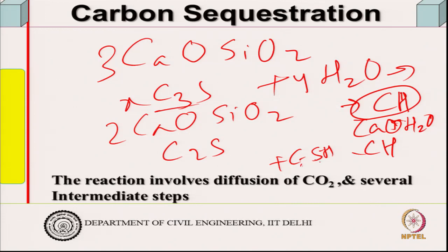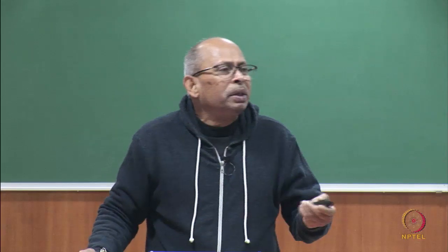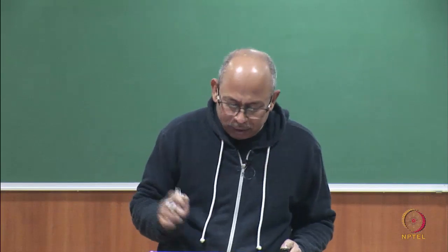This would be CSH here. So, this calcium hydroxide is produced. So, straight in the cement reaction, I get calcium hydroxide, and in the long run calcium hydroxide absorbs carbon dioxide from the atmosphere in presence of moisture and goes back to calcium carbonate state, and that in concrete technology we call the carbonation process, which reduces pH, etc., but that is not the issue here.